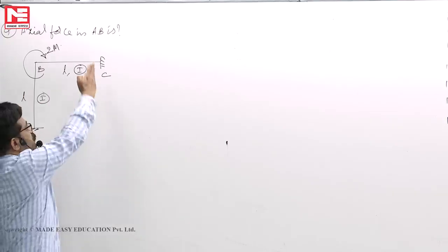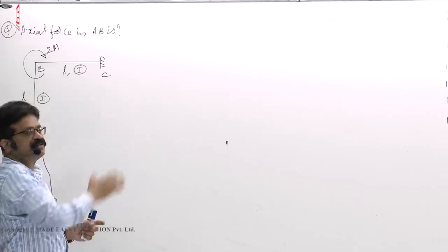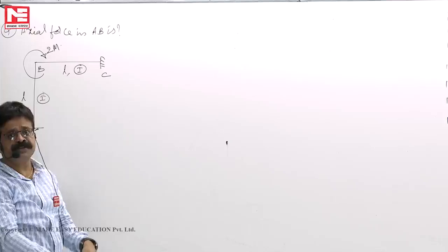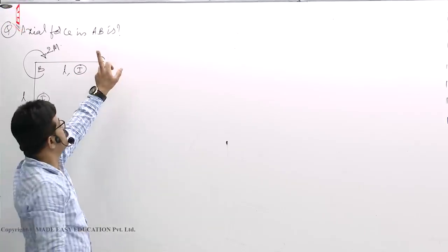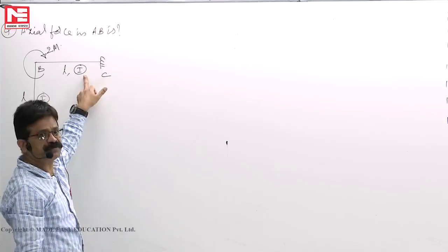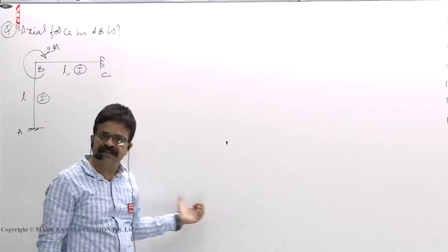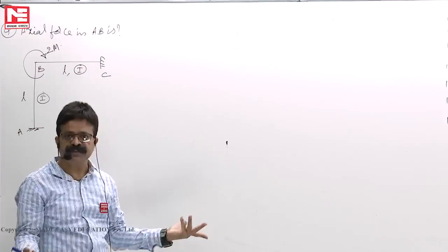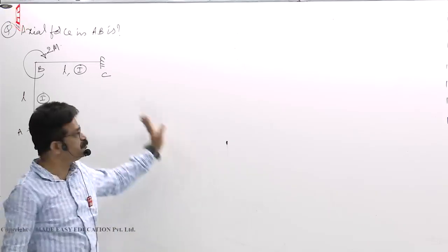At C, this is not a footing. Footings cannot be kept horizontally, it is a wall. Wall stiffness also infinite stiffness, we take it because 3 meters by 4 meters, big walls are there. So stiffness is very large, we take it. So wall stiffness 1, beam stiffness 0. 1, 0, 1, 0, 0.5, 0.5. So we should not write as I have written in the earlier problem, distribution factor, one is footing and member. You don't have to explain to anyone whether footing is there or wall is there. Okay. So second step is over.